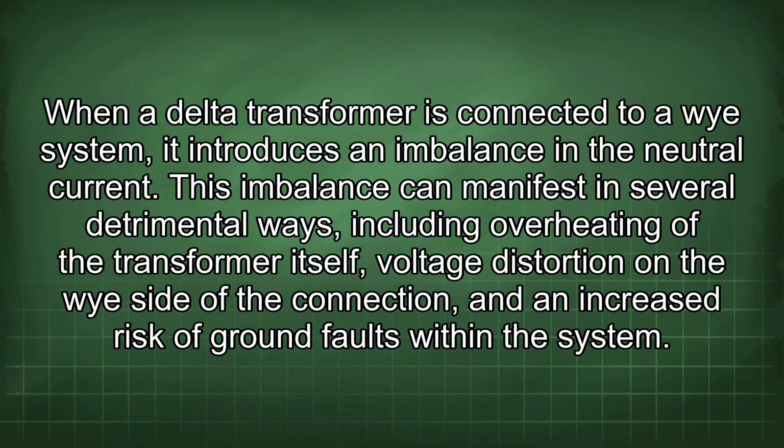This imbalance can manifest in several detrimental ways, including overheating of the transformer itself, voltage distortion on the Y side of the connection, and an increased risk of ground faults within the system.